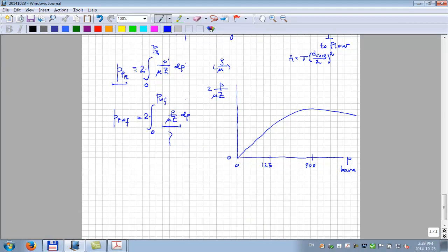But the point is that for a given gas with, let's say, specific gravity or known composition, this curve is given once and for all, from day 0 to day 50, 60 years later when we finish producing. It's the same curve every time for that reservoir, for that gas.